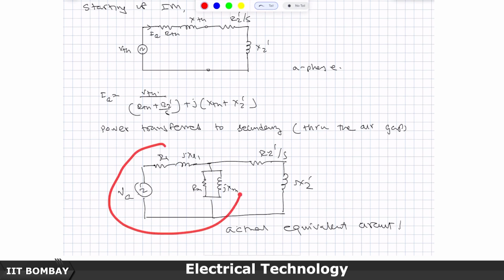We had said okay, let us treat this as the load terminal. Then we measure the open circuit voltage here, we call it V Thevenin, which is basically this whole series, calculate this series impedance and then, proportionate to this, find out that voltage, and that we called the V Thevenin voltage here.